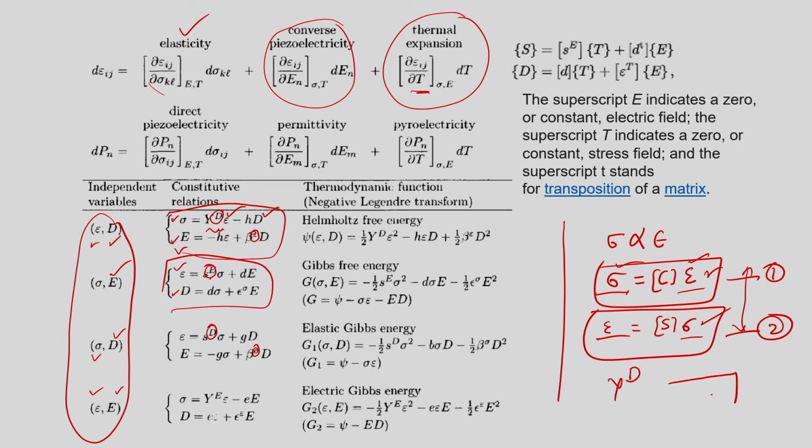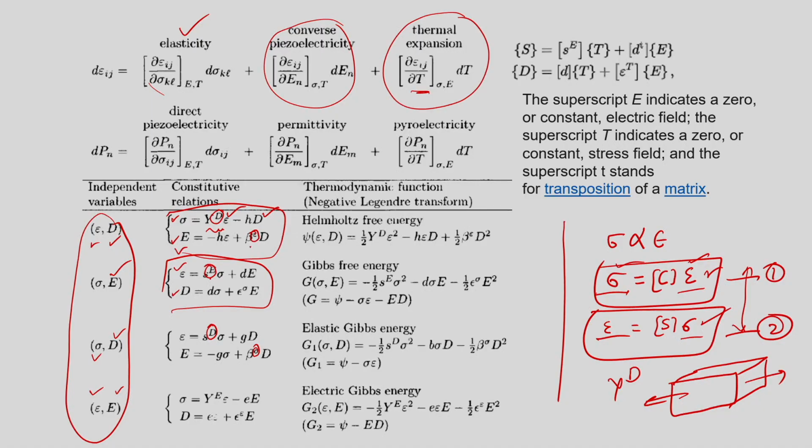When you study, you find out electrical or mechanical properties. These mechanical properties sometimes change with the electrical field. So, if I say that with a constant strain, this electrical field, this property, this beta, is obtained having the constant strain, or if we say that this Young's modulus is obtained when we subject a sample under constant electrical displacement.